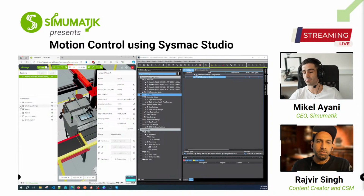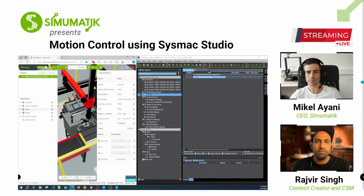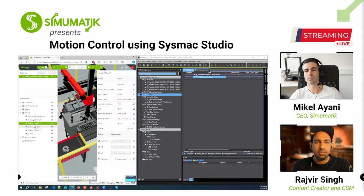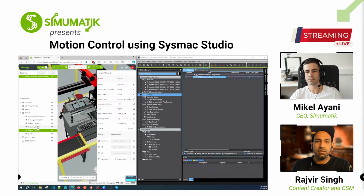Maybe here, you can also mention in the drive, we have this relation parameter. I had to use it. This is default 1.0 when the audience is using it. But I had to change it because in Omron I had a unit of millimeters, and in Simumatik we had meters. So you can easily convert these units using the relation parameter. Conveniently.